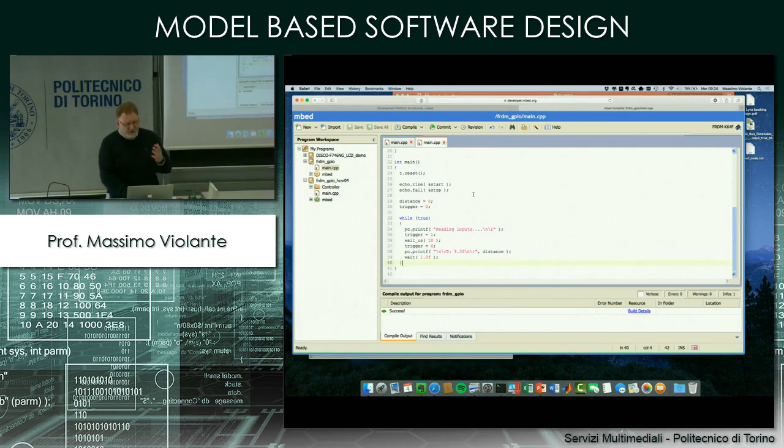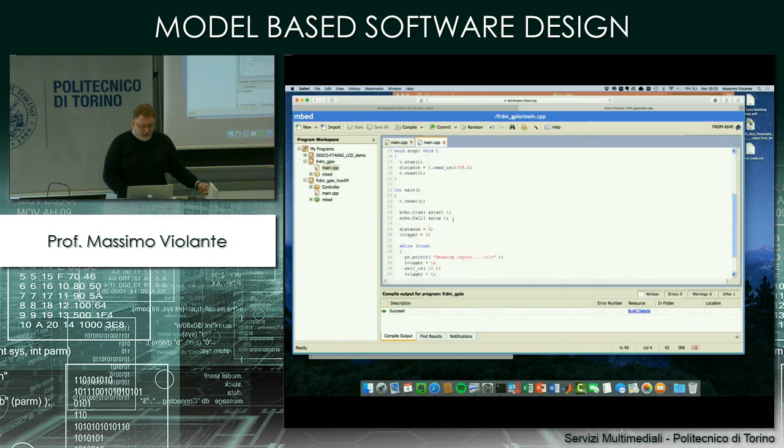So, what's the benefit of using this approach? Well, we can handle much faster resources that cannot be handled using full executable export. This is because by adopting C programming, we can access the low-level details of the board, like, for example, the interrupt, the capability of generating very narrow pulses, 10 microseconds, and the capability of using a hardware timer. These are resources that are not allowed within the platform support package because there is no support for those resources in the platform support package. Okay, so more flexibility. On the other hand, more complexity, because you can see here we need to do some C programming. Okay.